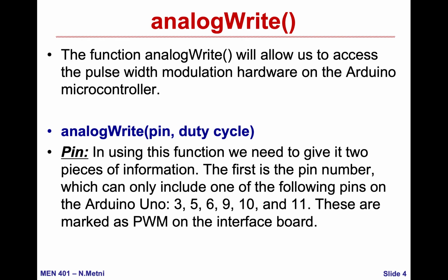Basically, in the Arduino Uno we do not have an analog output, so we will not be able to output any voltage we want from 0 to 5 volt. However, as we saw when I discussed the digital to analog converter, if I do not need an exact analog value, we can output a digital signal that the device will understand as an analog one. The only way to do it is through a pulse width modulated signal.